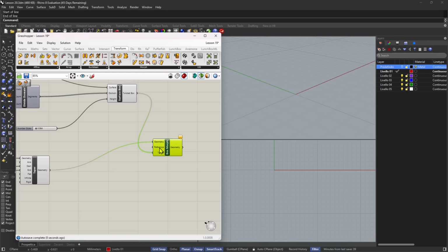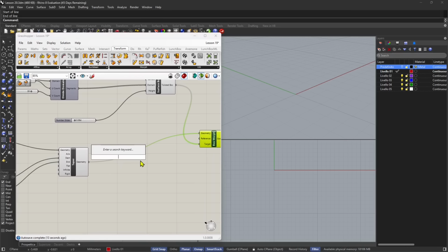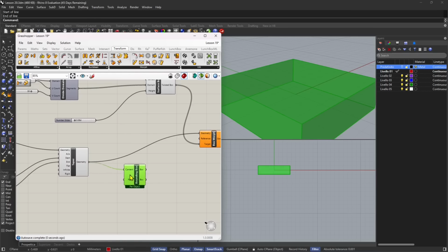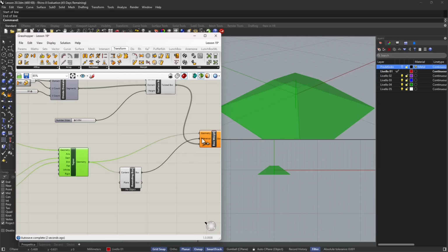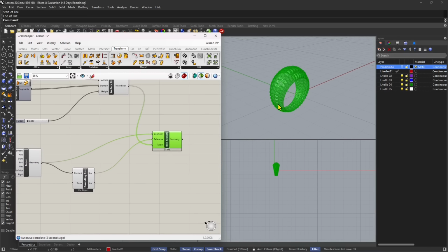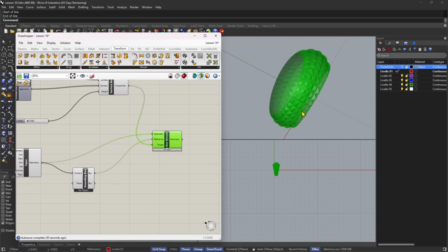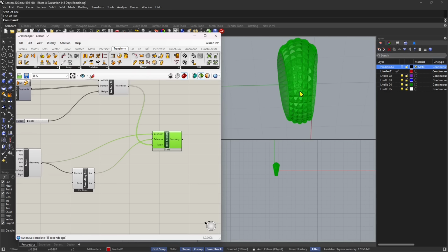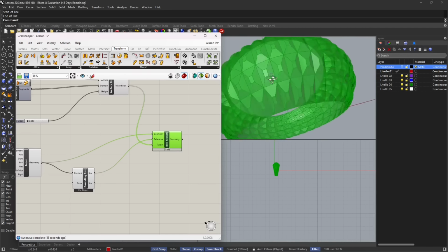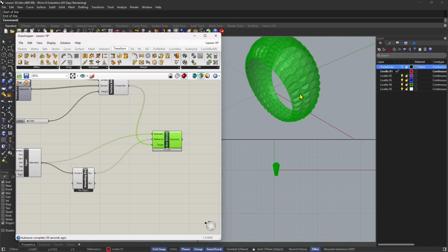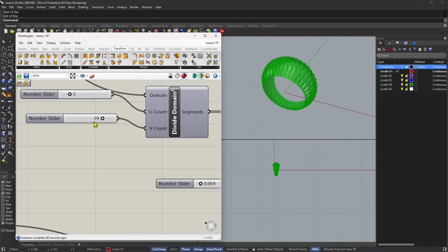And it's missing again something, which is the reference. Now for the reference, we want to create a bounding box, and we want to put into the bounding box the geometry again, the stud geometry, and then plug it into the final result. And you can see now it's distributed. So this is the first task, to distribute. And you can see that where you have less space, it's going to squash, and when you have more space, it's going to stretch. So you need to find a shape or something that can adapt, and it's also nice to look at when it stretches and when it gets smaller and bigger.